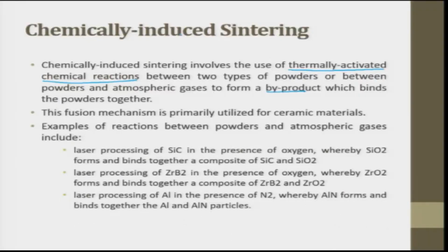Okay. Chemically induced sintering involves the use of a thermally activated chemical reaction. Here there is a reaction, but in the laddu example there is no reaction. A thermally activated chemical reaction between two types of powders, or between the powder and the atmospheric gas, forms a byproduct which binds the powder together.